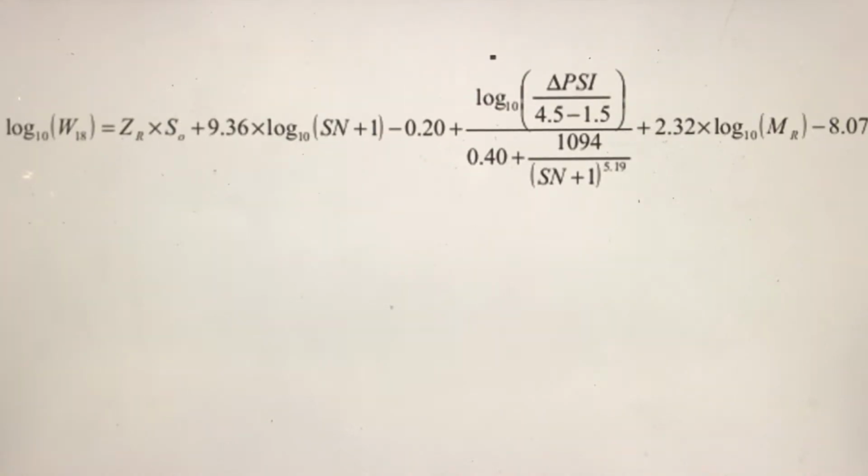The southbound pavement design was calculated first. Multiple iterations were taken to acquire an accurate structural number value. Constants such as the reliability and standard deviations were taken from the FDOT Flexible Pavement Design Manual. The soil resilient modulus was acquired from the state's materials office.